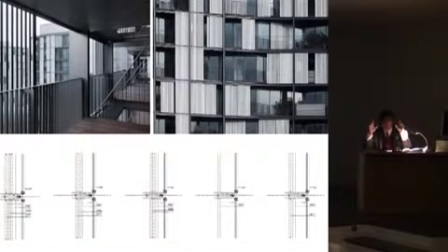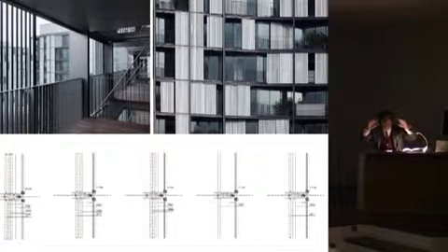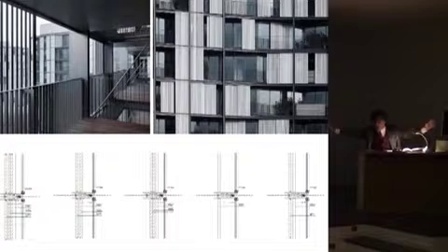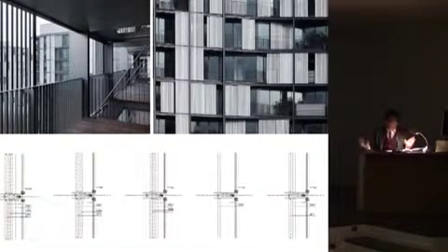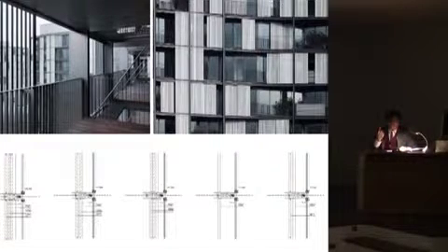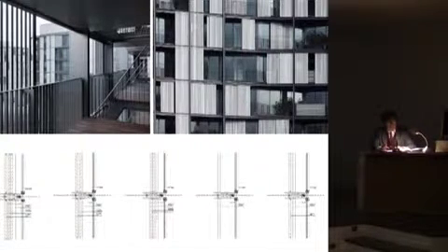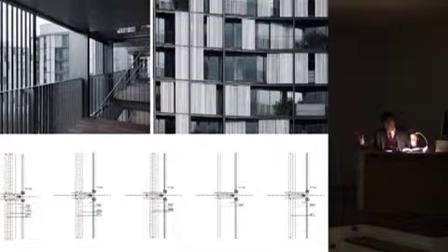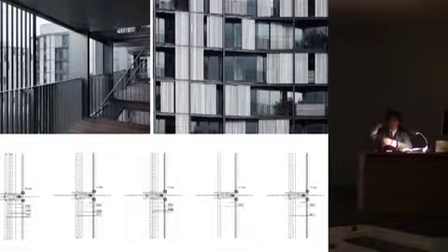You know, the gutter slope, Pere Llimona used to say that was horror. He always used flat gutters because imagine, tile roofs and a drain pipe there, disaster. So flat gutters, but you need to prepare for that. It's best to have many small pipes because if they become clogged because of, I don't know, a ball or a pine needle, everything goes onto the drain pipe. But there are many, so you have on a terrace one at each side, and they can be